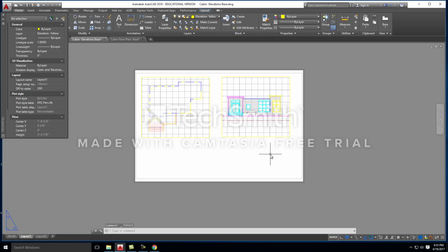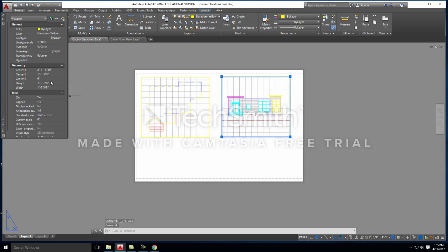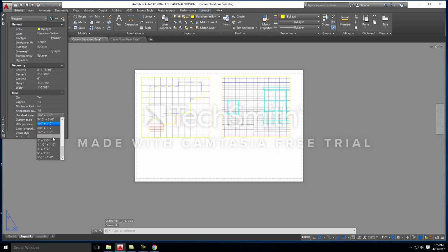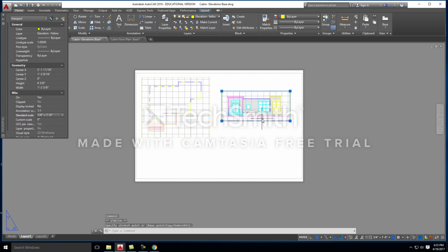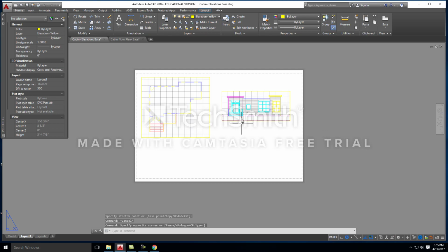All right, go ahead and click out of it. Make sure that we still have a 1/4 of an inch scale, because it is very easy to accidentally make it not to scale as soon as you click inside that viewport. All right, I'm going to bring my viewport extents down, and I'm going to do the same thing. I'm just going to copy and paste this down.